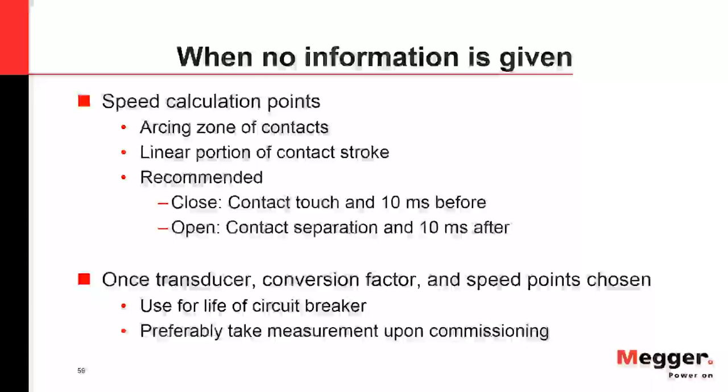So a couple of things. Time and travel analysis is critical. Not only time, but travel gives you overtravel and stroke, it verifies the dashpot is working, and it verifies that the velocity of those interrupters is correct.